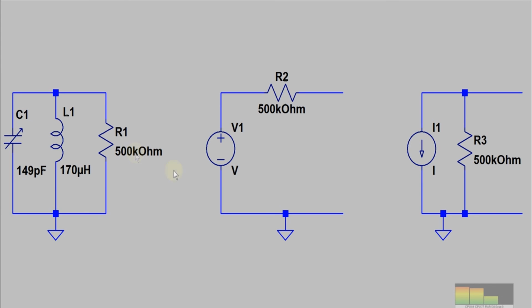And this is of course important when it comes to radio reception, because we want to know, first of all, how large is the voltage that is generated in the tank circuit by the electromagnetic waves. And what's still more important, what is the output impedance of our voltage source?